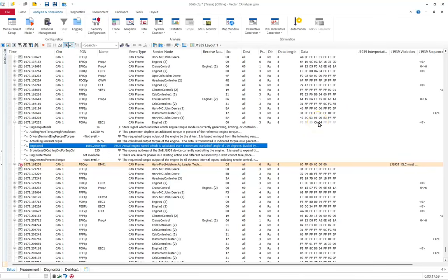So the tachometer on the machine knows to look at this particular message, which we call a PGN, a parameter group number, from the engine controller, and it knows to look at these 2 particular bytes and knows how to scale and decode those to convert that to engine RPM.